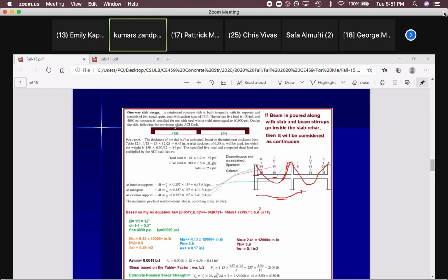Because it's reinforced concrete, it should be actually a little heavier. So we will consider 150. That's the unit weight of the reinforced concrete times thickness will give us pound per square feet. That's the uniform weight of this slab, everywhere on this slab. Then times 1 foot, we change that to pound per foot. And we are using that here, divided by 1,000, kip per foot, because we check for 1 foot width of that slab. Is that clear? So we always should use 150, right?